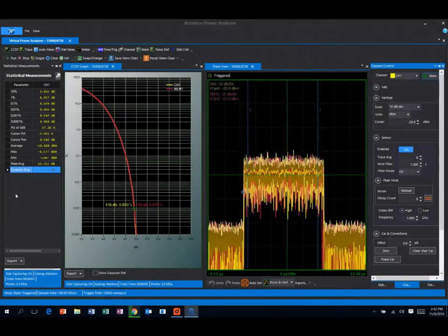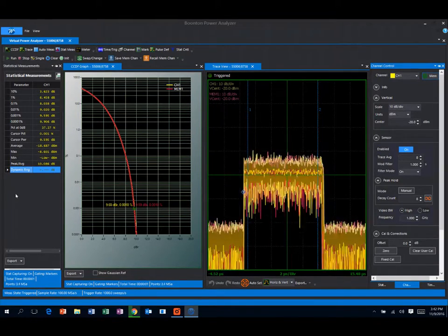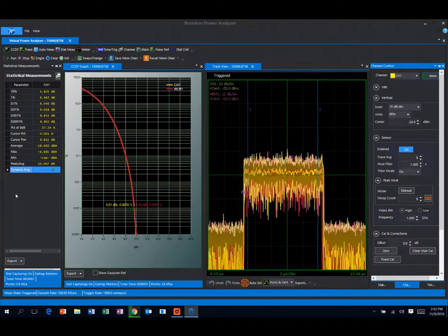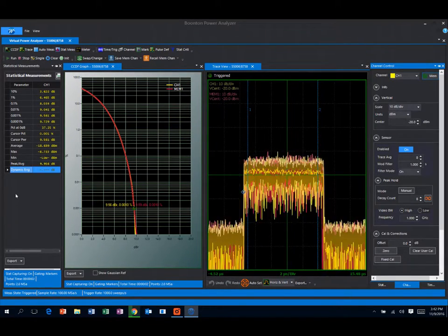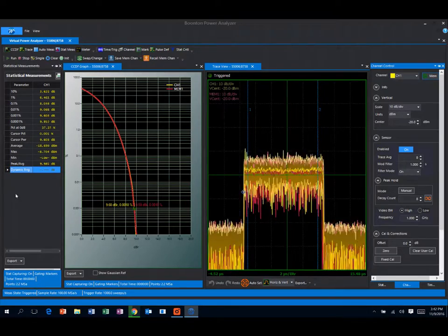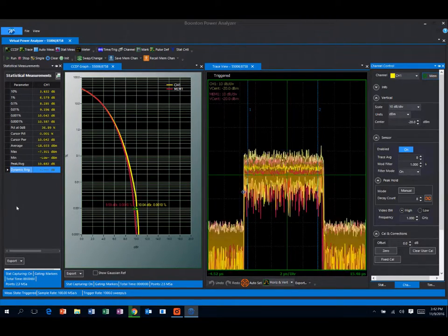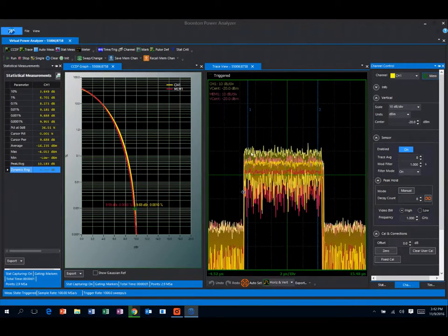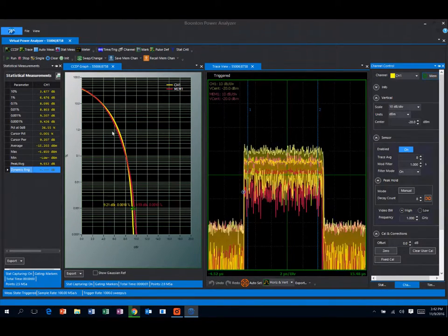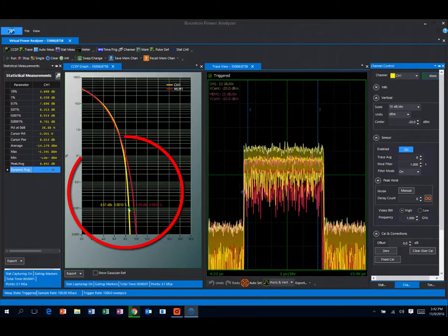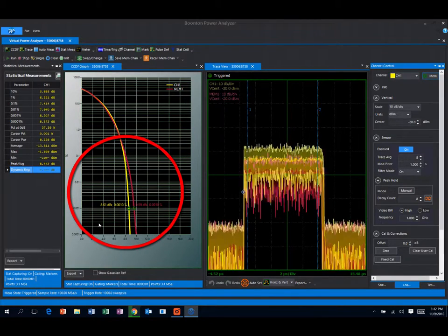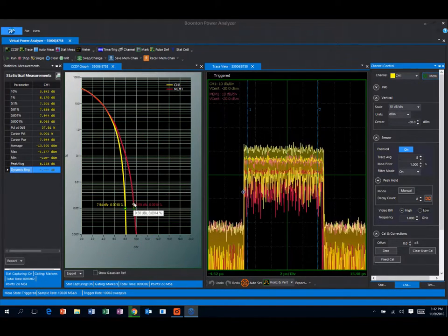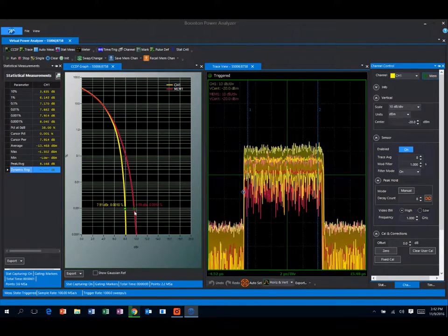By driving a limiter, which can be used to protect an amplifier or distributed antenna system type of products against overload, I'm going to drive the limiter by increasing the amplitude into the device. And what I'm seeing on the right hand side is my pulse power starting to rise while I'm looking at the CCDF display and seeing that I'm starting to get some separation down here. This is showing that we're actually causing potential bit error rate in our device or communication systems.